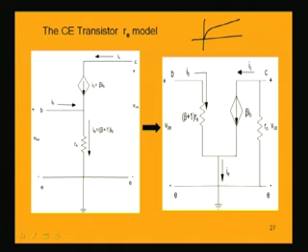So, ro will be there. In fact, the value of ro is in the order of mega ohm, but still, to have an exact representation of the common emitter transistor, we must include it here. That is why it is not ignored, since it is not infinity. But in common base, we conveniently ignored or removed it, because it was almost infinity owing to the horizontal curves, but here it is not horizontal. That is why the slope has to be represented, and it is represented by this output resistance. Of course, this value is high. So, now this circuit also has the resistance ro. If I look into this resistance, the current flowing through it is beta plus 1 times IB.